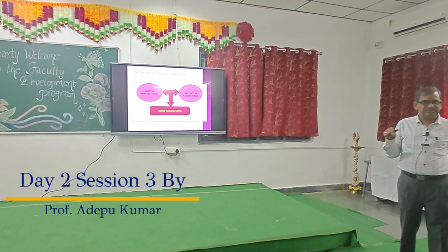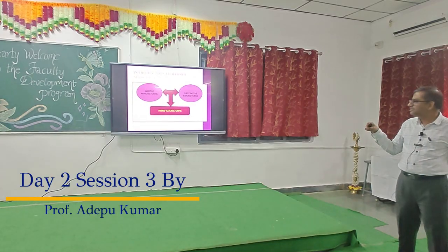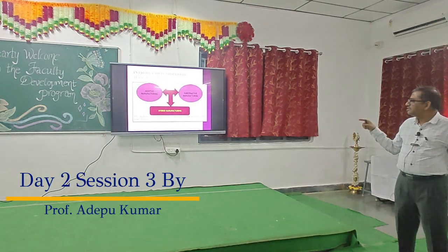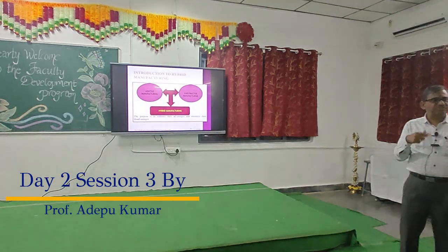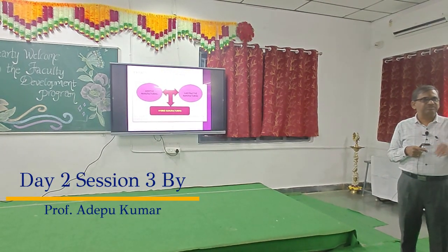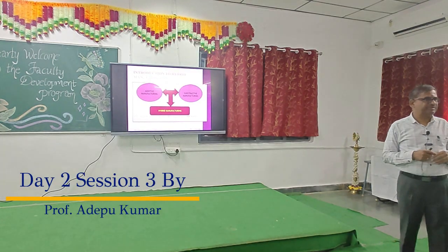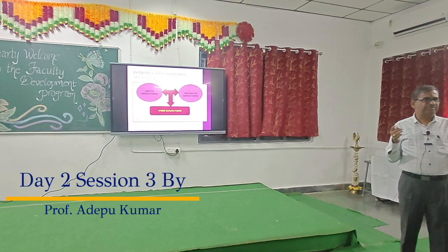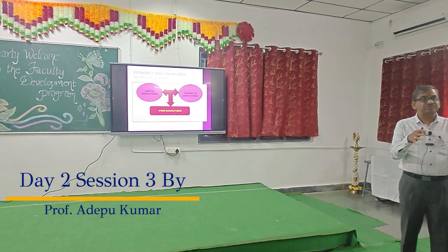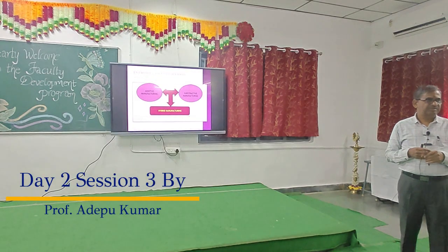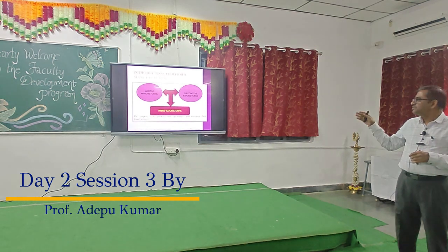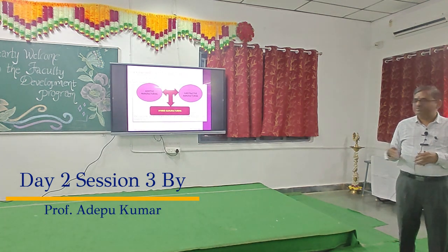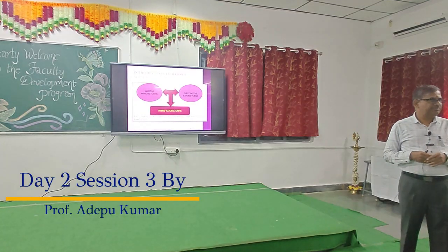You are adding the material by melting the filler wire layer by layer. And after deposition, you need to finish the component. For that, you need to remove the unwanted material from the deposited component. That's why you can go for a subtractive manufacturing process. So with the combination of additive and subtractive together in a single machine, you can save setup time, so that you can reduce the lead time. That is known as the hybrid manufacturing process.